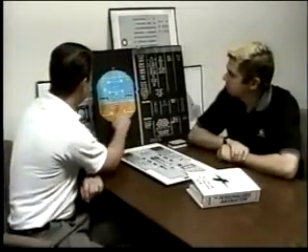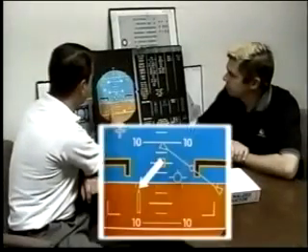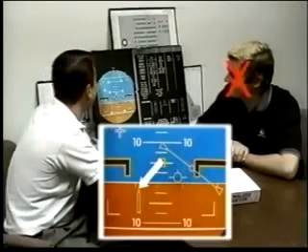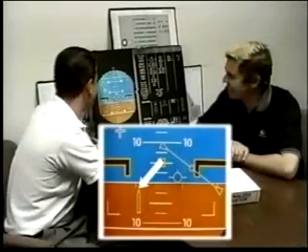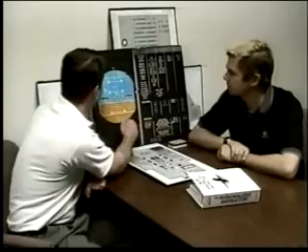Staying with the ADI, what's this green pointer? That's called the Washington Monument. Let's be more specific. That's the ground roll guidance command bar. Is that always displayed? No. Actually, it's displayed only on the ground up to 30 feet during a landing or a takeoff on a runway with a localizer. Okay, so it's receiving a localizer signal.